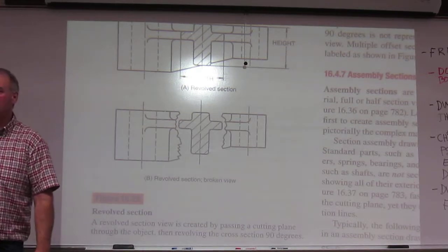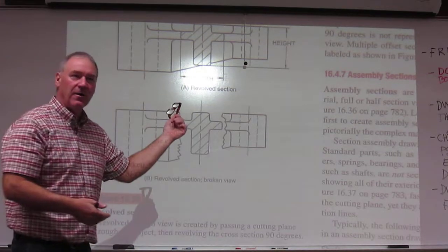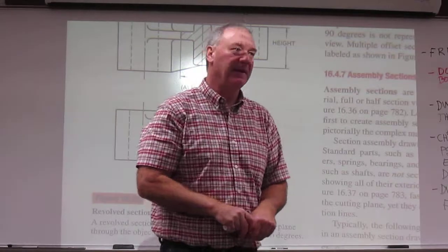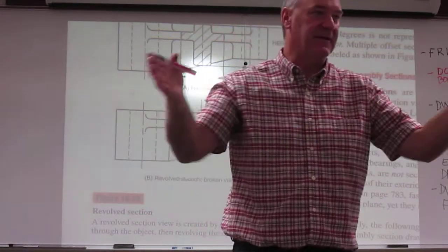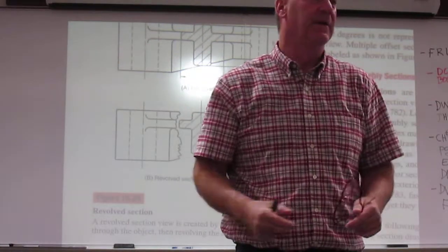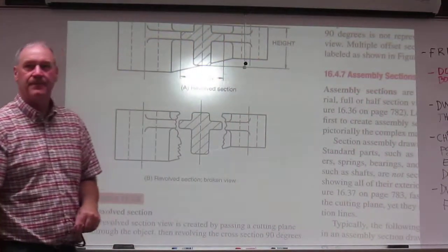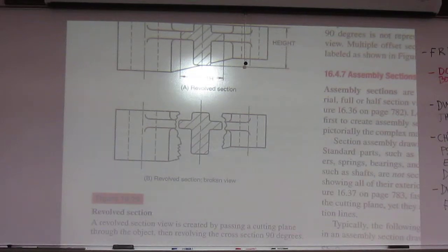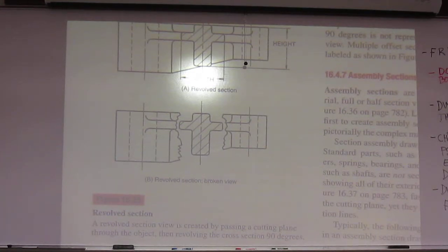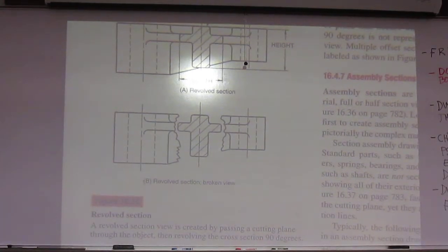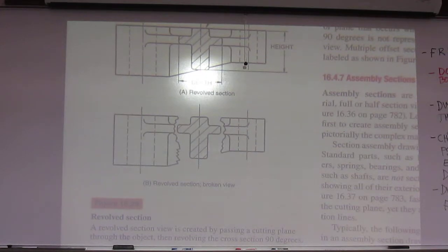This would work great on shovels, arms like this, flywheels, anything that has a structural component that's holding two items together. The revolved section is a really good section to pull out. Take a thin slice, put it into the view, rotate it 90 degrees.